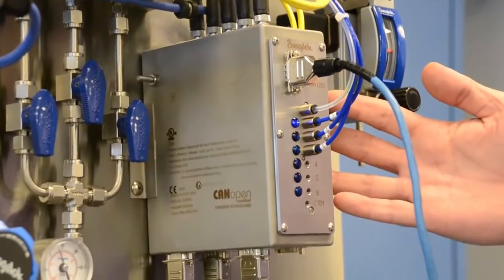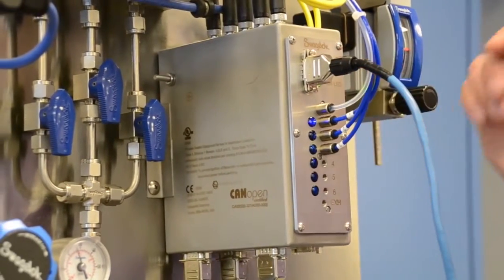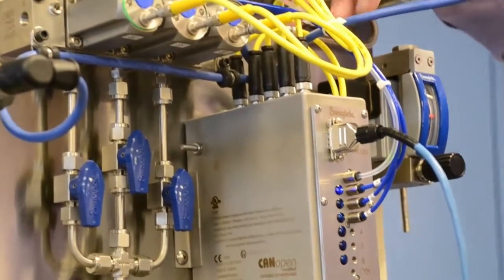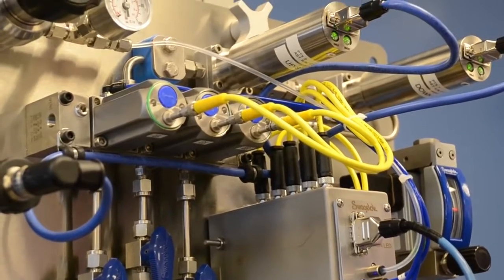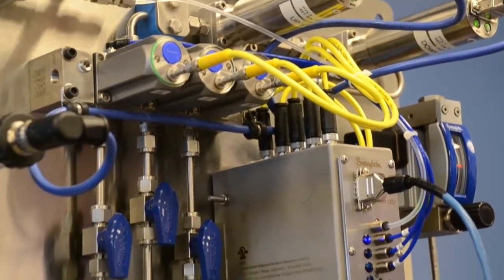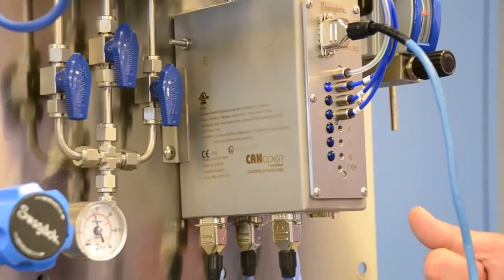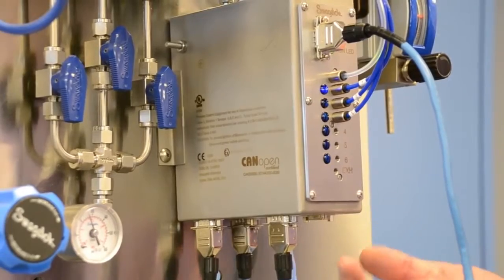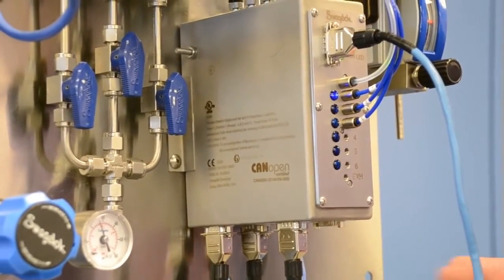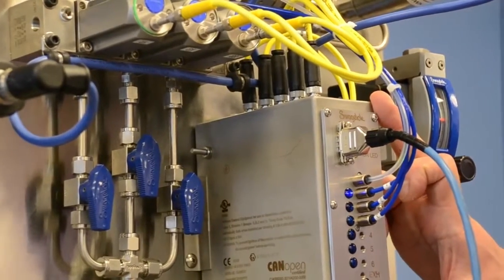So with an ICM, you can actuate valves with its pneumatic outputs, you can monitor digital inputs with its digital inputs, and you can monitor and power your sensors with its analog ports. There are 4 ports on the bottom of the ICM. Each port has both voltage inputs and a current input that make it versatile for use with a wide variety of sensors. Now the Intelligent Control Module is intelligent.